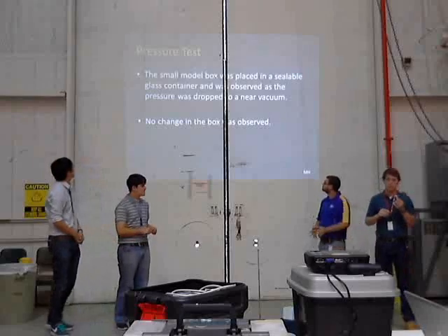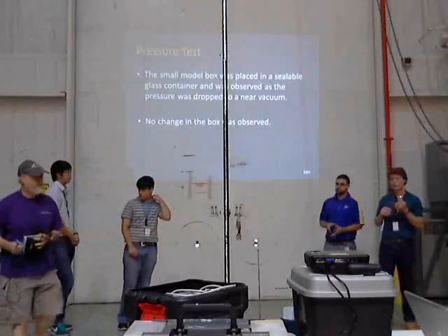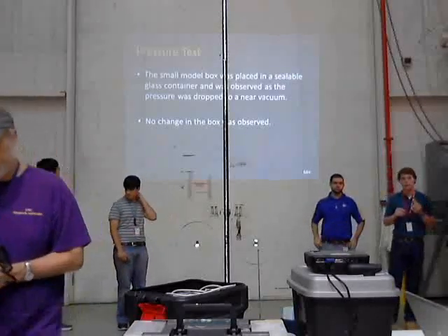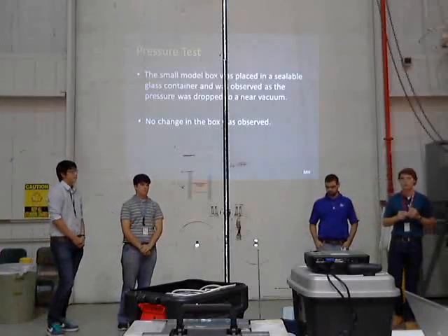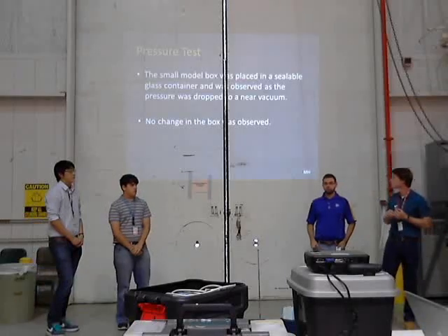For the last test we did a pressure test. We placed it into a glass container and dropped the pressure to a near vacuum. We noticed no changes, so we concluded that our box will withstand the low pressures of the high altitudes.